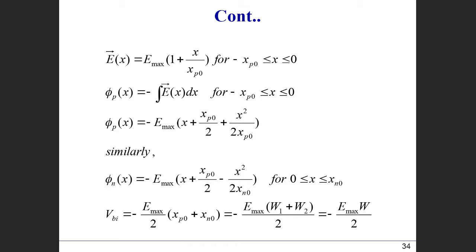And then, as I mentioned, the potential difference in here gives us this VBI, built-in potential. Okay, and then in terms of Emax, we can also have the built-in potential for this particular case. We have this kind of formula in here. Okay, again, this formula still assumes that the charge distribution throughout the PN junction is a step junction.